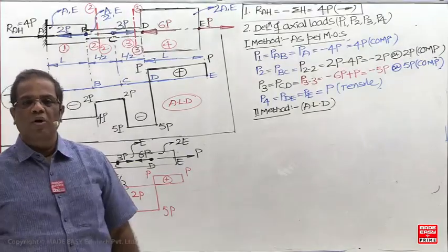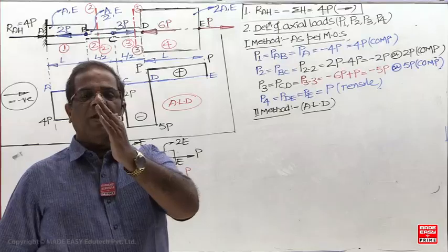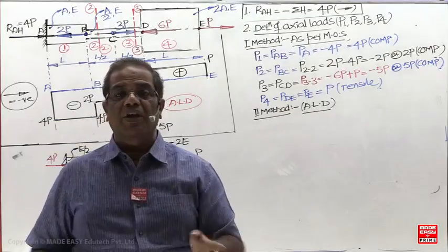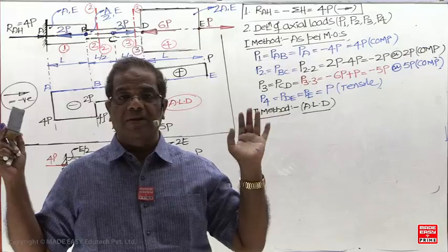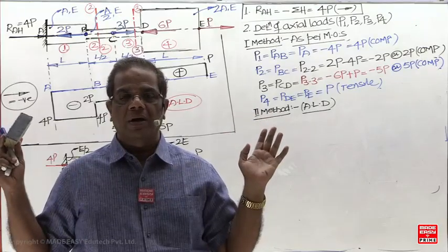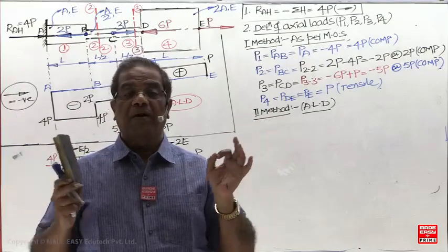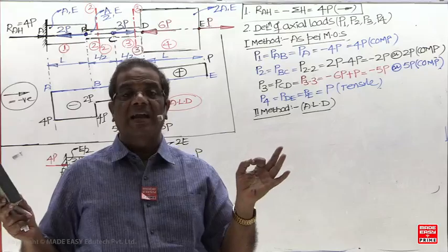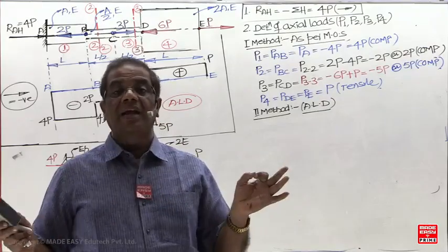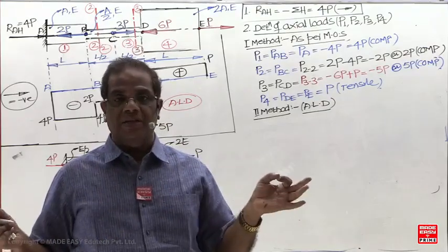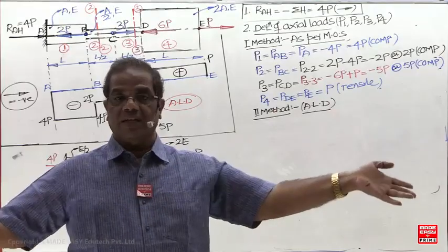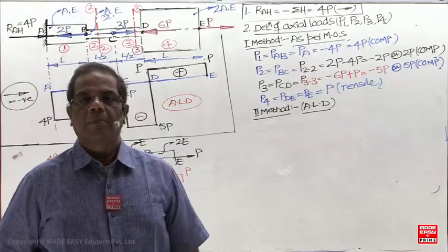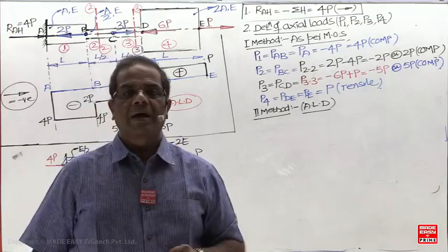What is the definition of the load written here? Algebraic sum of the load either on the left side or right side, where you are not considering the material, where you are not considering the cross-sectional dimension. This is a very important conclusion now. Shape of the loading diagrams are independent of the material, independent of the cross-sectional dimensions, and independent of the shape of the cross-section.